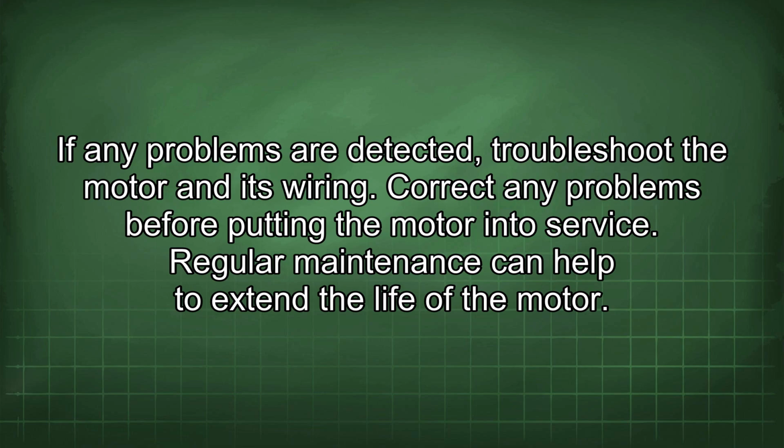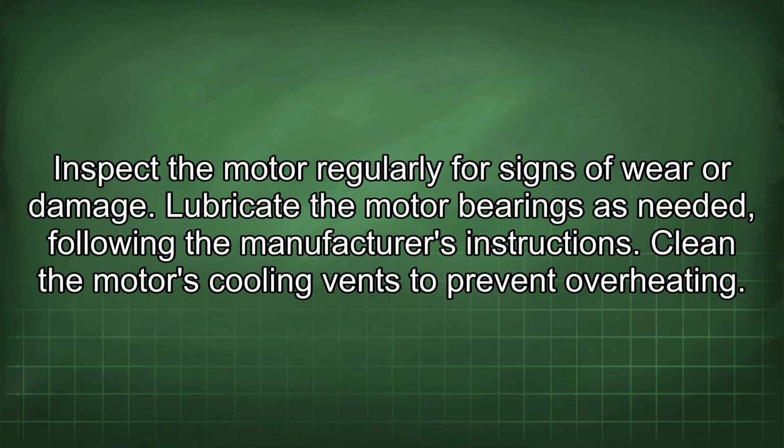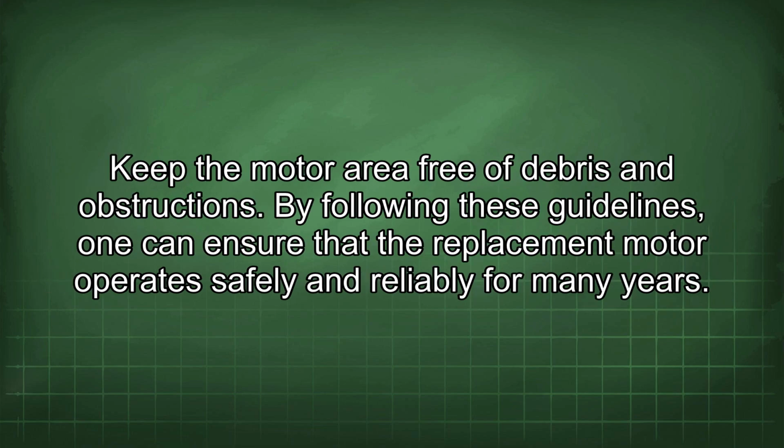Regular maintenance can help to extend the life of the motor. Inspect the motor regularly for signs of wear or damage. Lubricate the motor bearings as needed, following the manufacturer's instructions. Clean the motor's cooling vents to prevent overheating. Keep the motor area free of debris and obstructions. By following these guidelines, one can ensure that the replacement motor operates safely and reliably for many years.